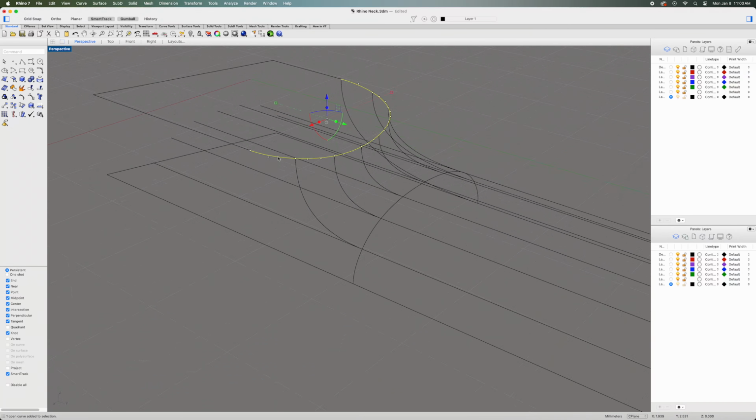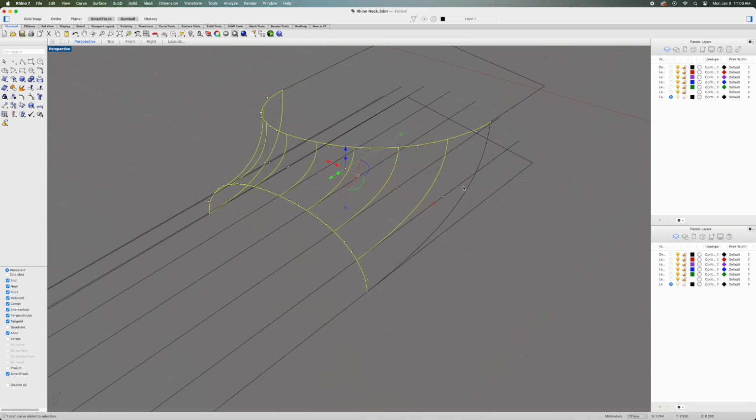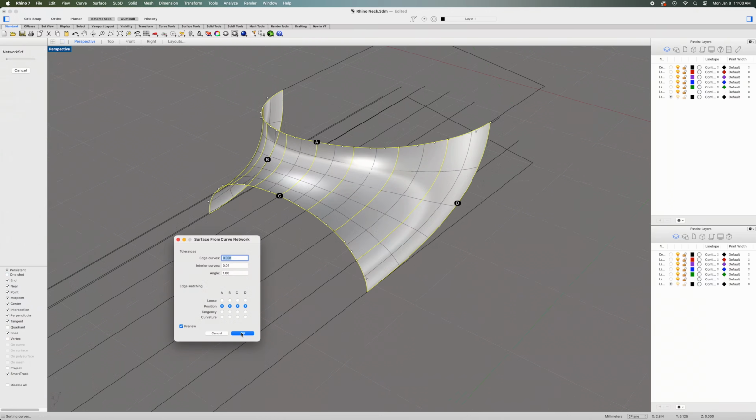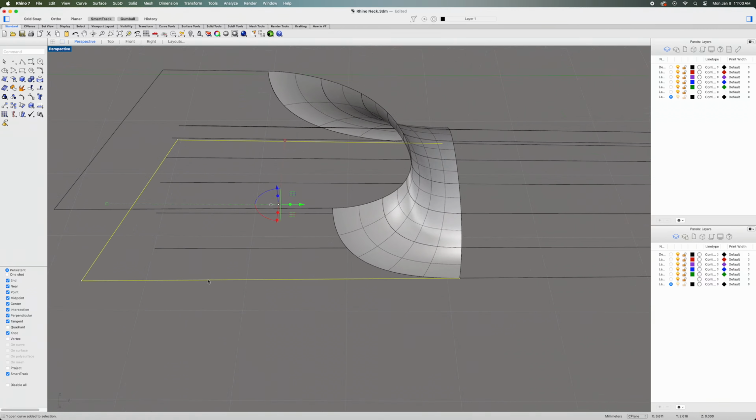And then I will redraw that curve that transitions from the heel to that neck contour curve. So now I can select all these elements once again, and I'll create a new surface, which should hopefully not have that peculiar looking curl on the end of it. I'm not sure why Rhino does this, but it does. And as you can see, it's now a perfectly formed surface shape.